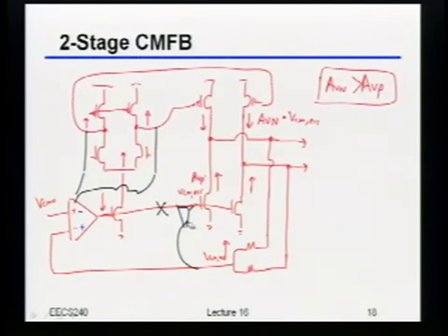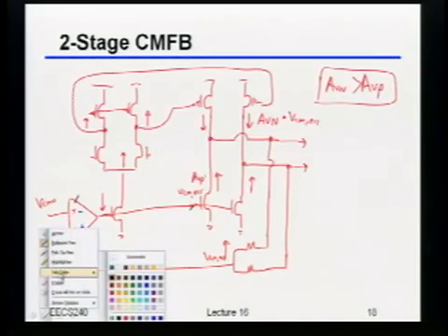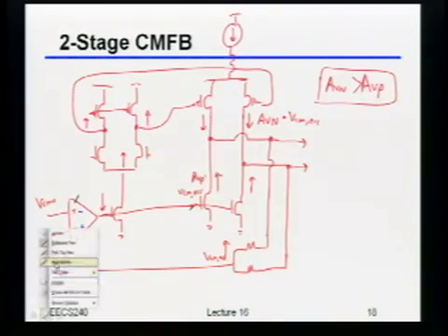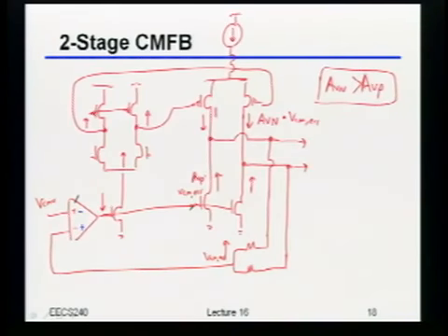Okay, any other thoughts for something that you might do that, well, I don't know if it necessarily solves the problem, but makes things a little bit easier to analyze? You can tweak the PMOS sources of the first stage. Okay. So basically, you could do something like add a current source up there, right? So that instead of having a pseudo differential design right there, you actually have a fully differential design. Why does this help, by the way? What's sort of good news about doing that?